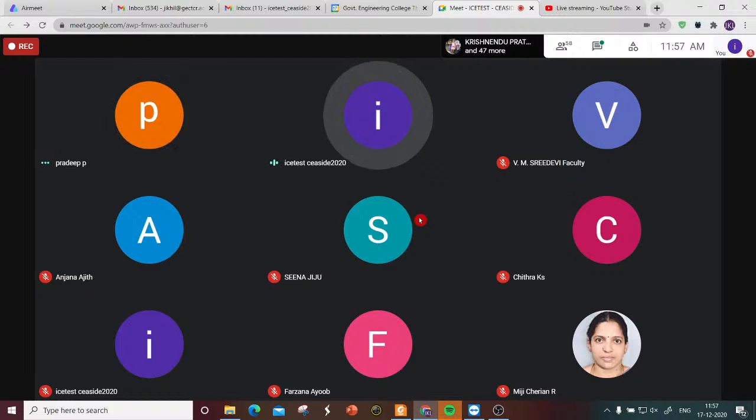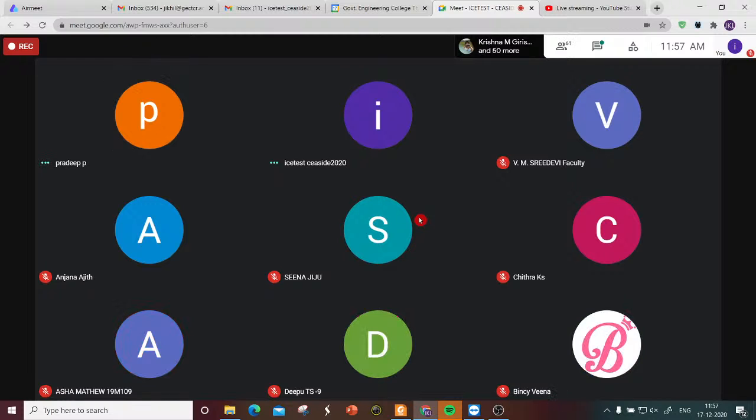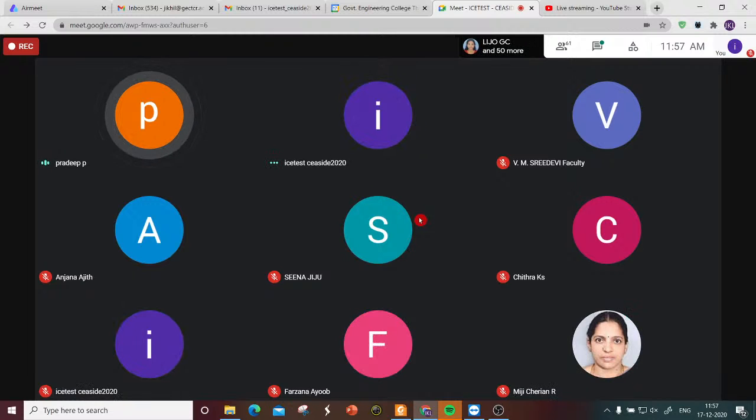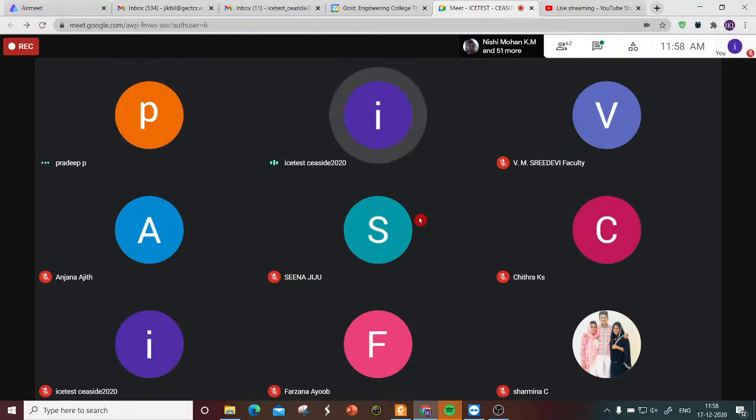What about the specific gravity of this sintered fly ash aggregate? Specific gravity is very low, only about 2. So it's a lightweight one. Only the crushing strength is less compared to normal aggregate, but it satisfies the condition that the crushing value should not exceed 40. So we can't use this for reinforced concrete work because the gravity is very low, no? We can use it. It will give a lightweight concrete, and internal curing will increase the strength of the concrete. What about the density of the lightweight concrete?